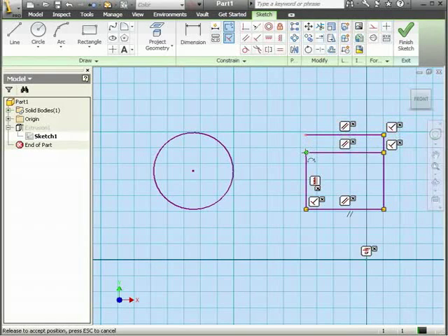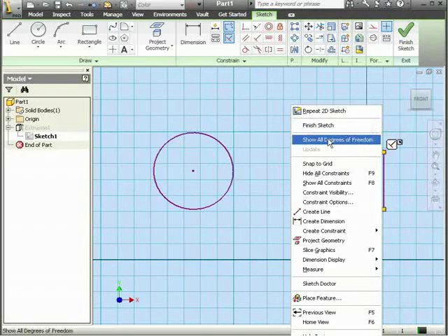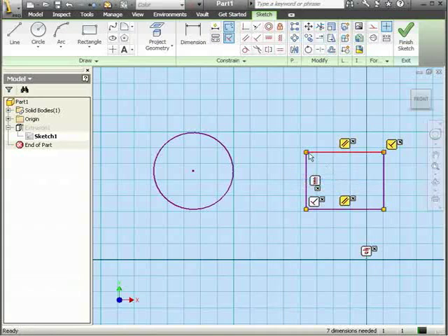Let's close this profile. We'll grab and drag the point over this point and drop it when the point becomes green. The coincident relation is back in place. Let's update the Show All Constraints to make sure. Right-click, Show All Constraints, or F8. Here is the coincident relation displayed.